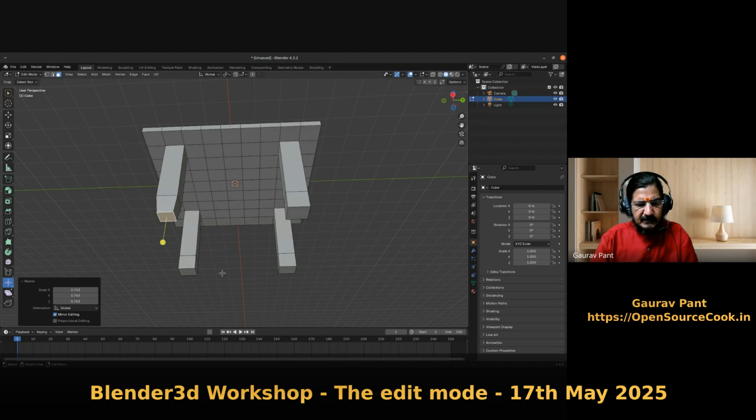it a bit small. Now I want to repeat the same thing. One thing is that if you know the keyboard shortcut, you could say scale it to 0.7 point something like that. But if you want to repeat this operation, then what you do is simply select the other face and press Shift R. Shift R is repeat the last operation. So this way I will achieve the same scale for all of them.